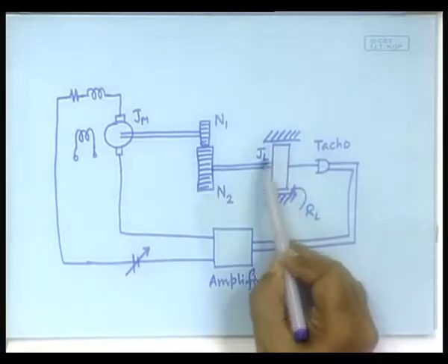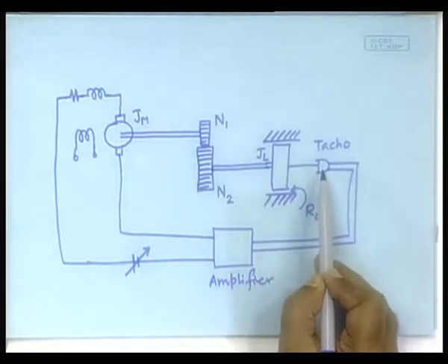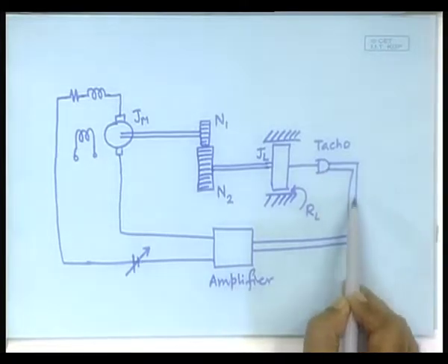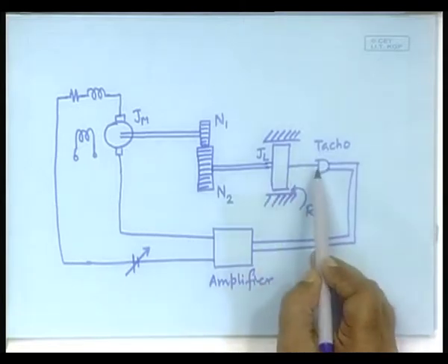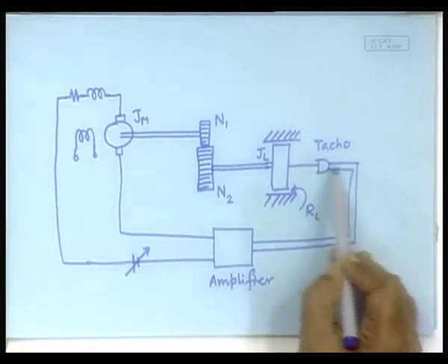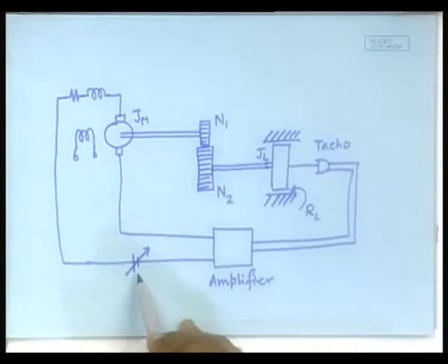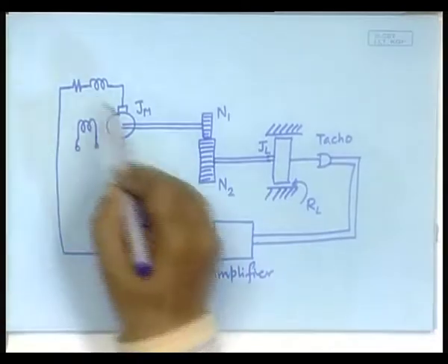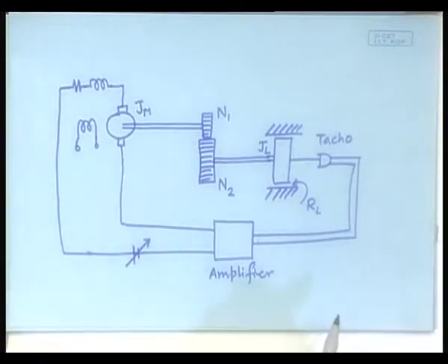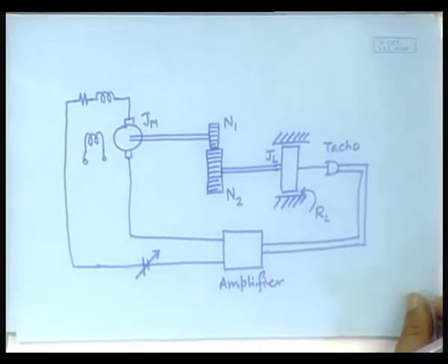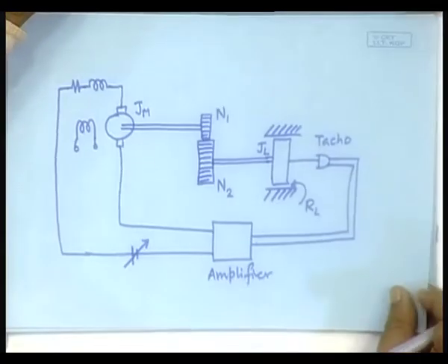So, you notice that here there is an observer, the tachometer is an observer. Observer of what? The flow, it is a flow observer. The flow information is coming in, but the effort information is not coming. So, that will give rise to an activated bond. This is where the flow will be converted into an effort information to be added to the external voltage, right. So, that is what will give the input voltage here, clear. This is a very reasonably practical electromechanical system. What was the problem number? It would be 9.